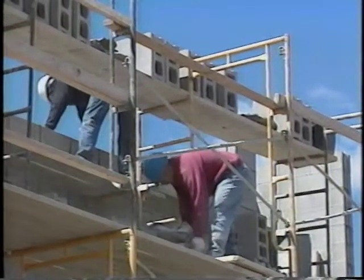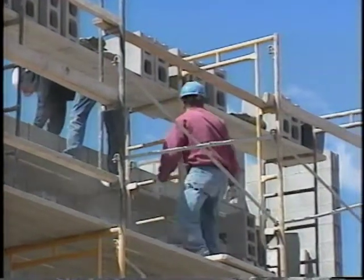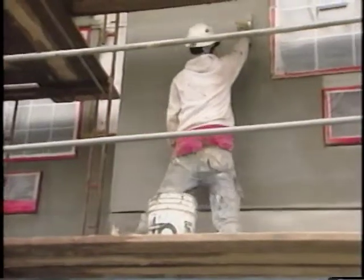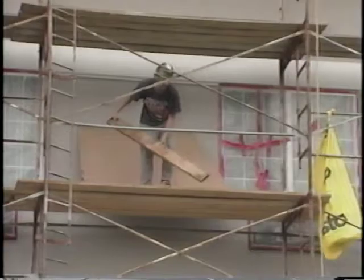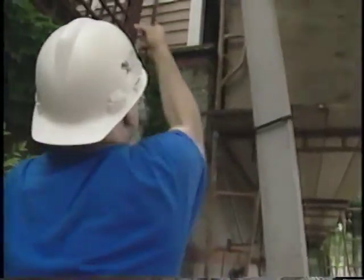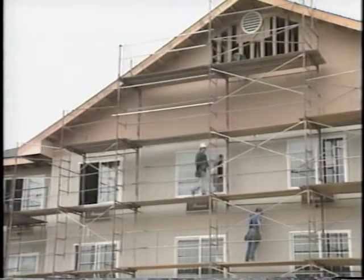Additional measures you can take to eliminate the possibility of a worker being struck by a falling object include keeping the platform clean. Store materials away from the edge. Never throw or drop items from the scaffold. Use a hoist, lift, or tow line to raise and lower material. Be aware of where you are walking on the platform. Avoid kicking or knocking material off.